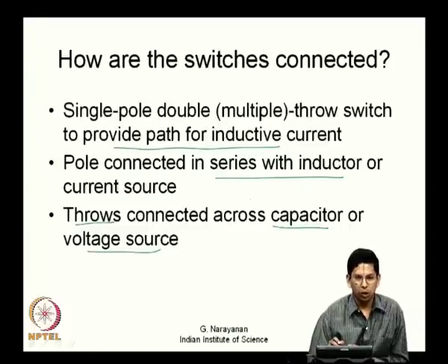If you look at more complex cases than a buck converter or a boost converter, you may not find a single pole double throw switch; you may find a number of single pole double throw switches. And there are also cases where you will find not single pole double throw, but single pole multiple throw, for example, a single pole triple throw switch. We will look at those examples a little later today. So, this is basically how you connect switches in a converter.